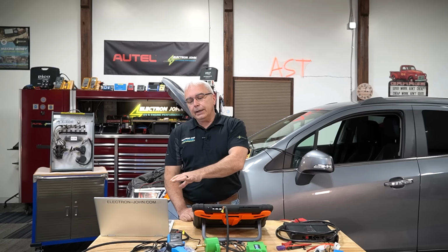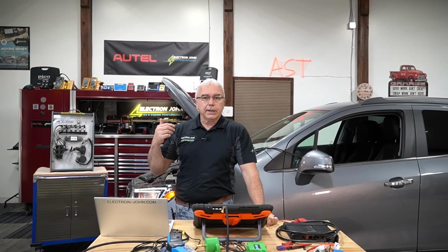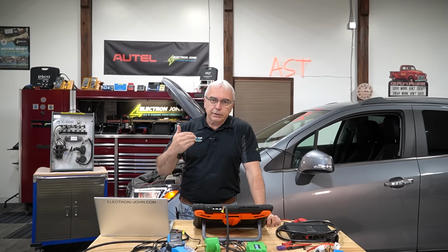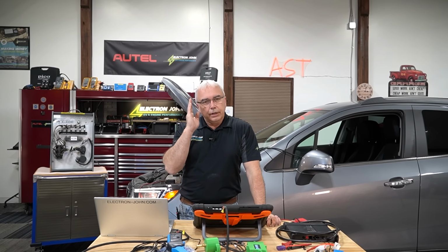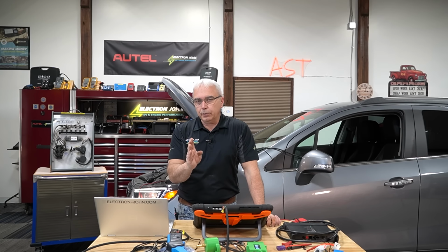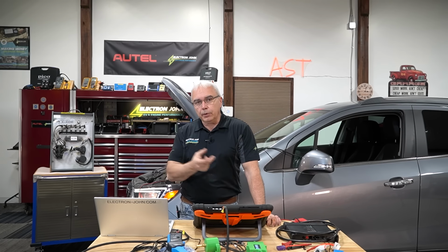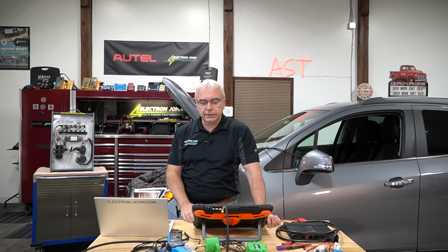So again, in the PowerPoint that we shared, we talked about it on one of the slides. If it's a 4-cylinder, 6-cylinder, 8-cylinder, let's say I triggered off number 1 as my firing input, I would have to count a couple exhaust pulses after that because it took that time to go out the tailpipe. Just wanted to make reference to that.